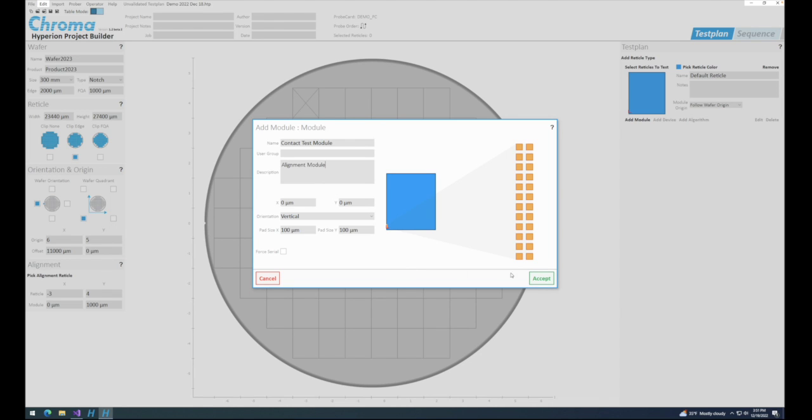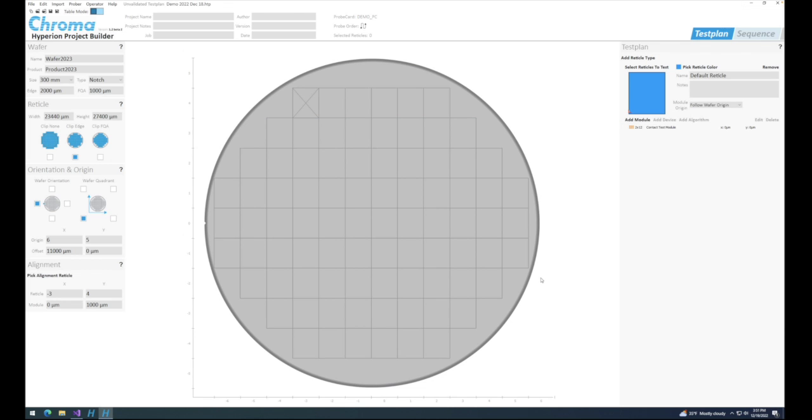The next field is the user group, which provides a naming system to optionally differentiate modules. For example, multiple modules of identical MOSFETs may be laid down for parametric tests, reliability tests, such as plasma damage, or other purposes. Setting the user group allows specific modules to be differentiated by these different purposes. The data taken on these modules will then be marked with the user group ID.